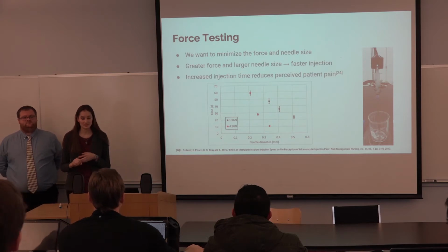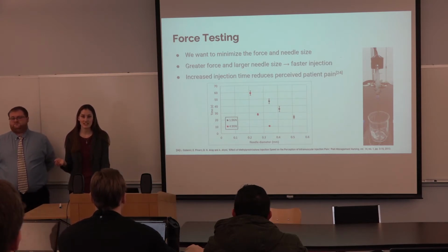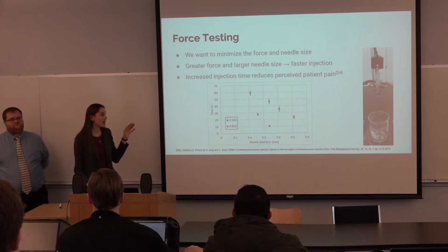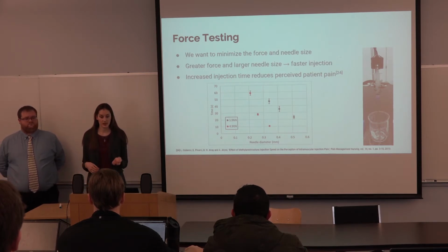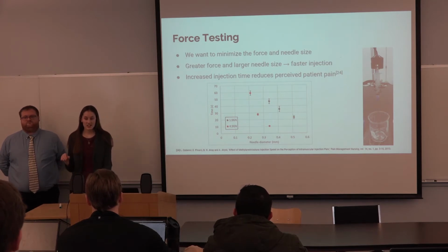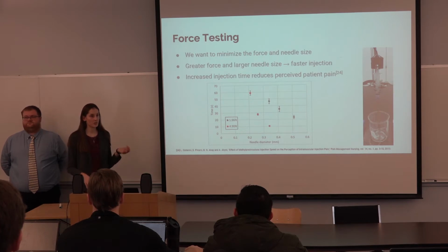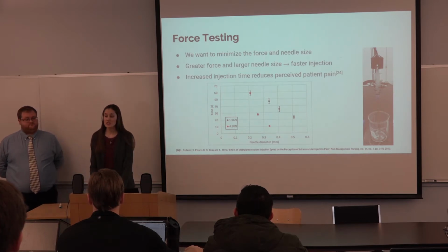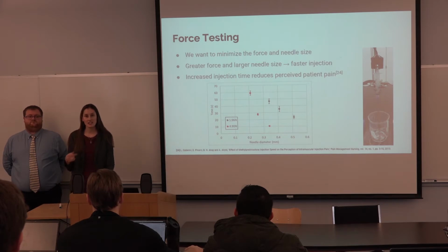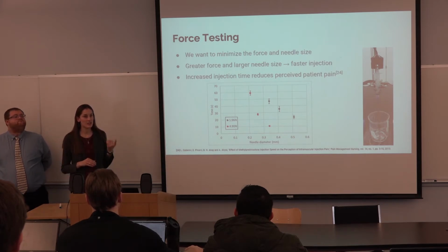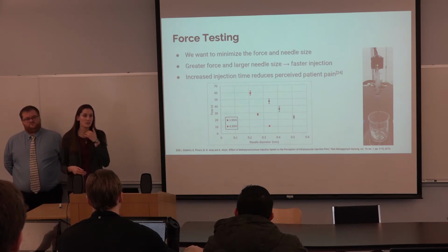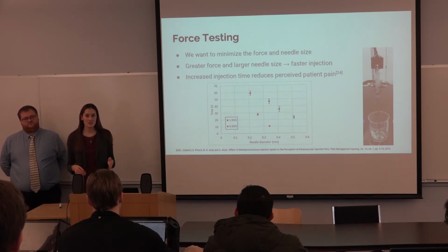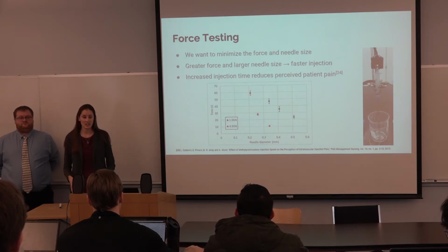injection would be. So if we keep the needle size constant, the time of injection is solely a function of the force, or the strength of the spring. This is an advantage of our design because we can tailor the injection time based on the strength of the spring we choose. Research has shown that increasing the injection time decreases the perceived patient pain. So the main difference between our device and current devices is that we will tailor the injection time to minimize patient pain while maintaining patient compliance.